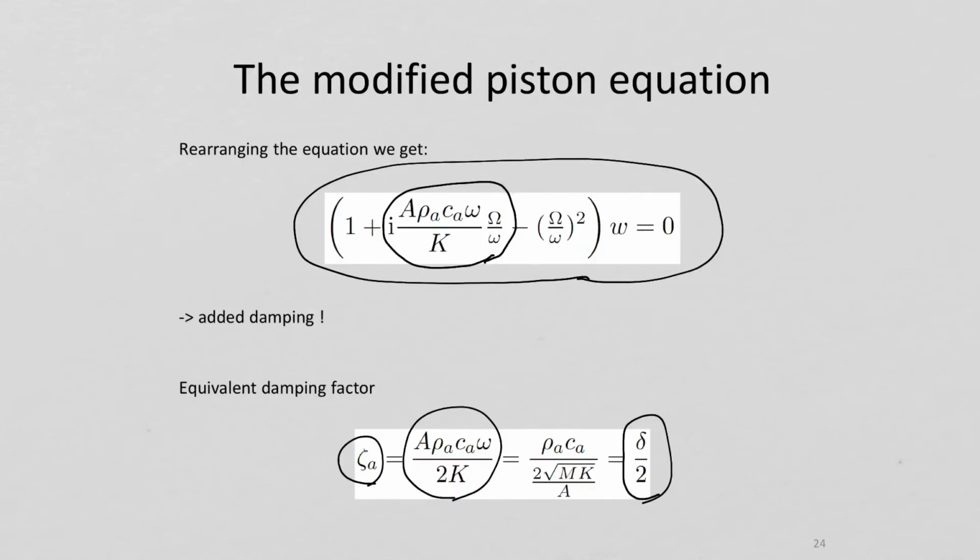Just going back to sum it up, we can see the basic effect on the piston motion of having an acoustic medium. If the end is closed, then we would have a change of the natural frequencies, and how much they change depends on the various parameters. It could be complicated if the frequencies are close and we have strong coupling. On the other hand, if our channel is open, then the effect is a little more simple. Then it just acts as a damper, and we can directly predict how strong the damper is based on the parameters.